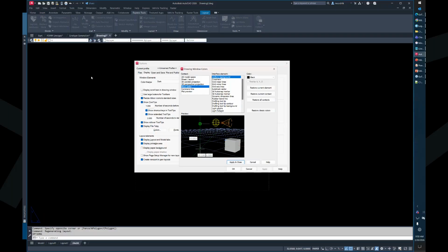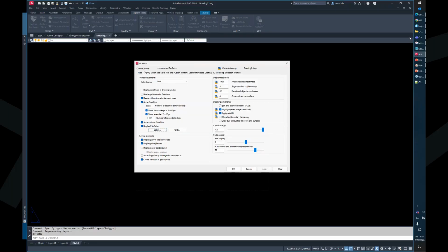Hang on, let my brain catch up with me. There is a command in Civil 3D that you can use to dump all the styles in the drawing to a text file. Export styles. Now you're gonna make me work. Let me think on that, Hunter, and I'll send it to you. There's a way to dump all of the style information into a single file, and you can work on it from there.